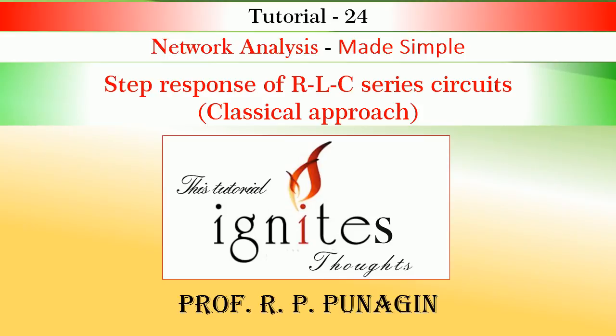During this tutorial titled Step Response of RLC Series Circuits, we shall develop a procedure to solve for complete solution for various parameters when the circuit is switched. In RLC circuits, you find that there are two energy storing elements. Hence, you will see that the system equation will result in second order ODE. The solution will contain two integration constants. We shall establish the procedure to obtain the two integration constants and solve for few examples.